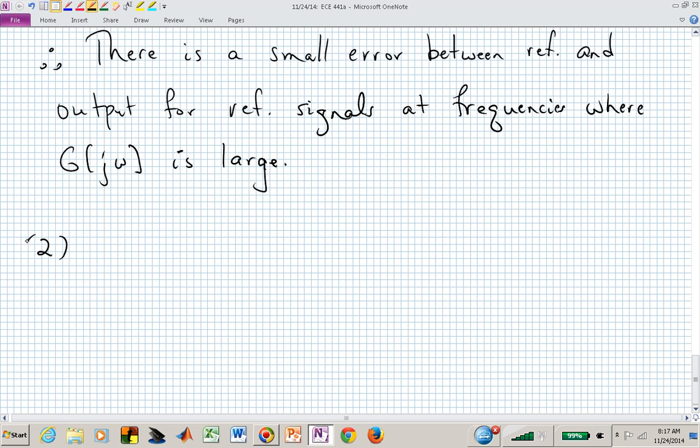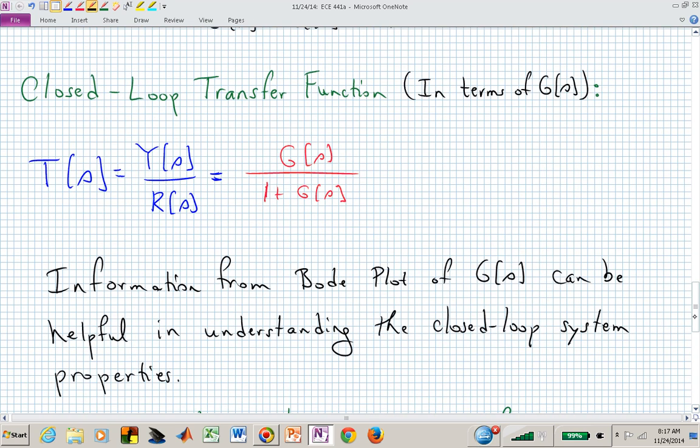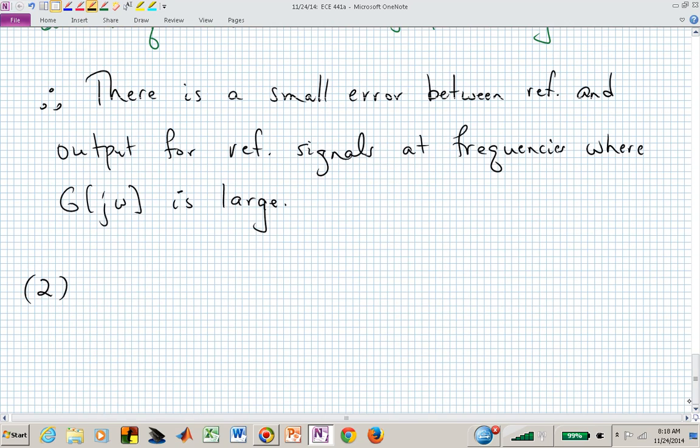Another point that we can take from the open loop is, if I now ask you, looking at the closed loop, typically the first thing I'm wanting to know is, what's the stability of the closed loop system? What impacts stability in this transfer function? Which piece of all the pieces that are there influences closed loop stability? 1 plus G of S. Now the frequency response is looking at G along the imaginary axis.